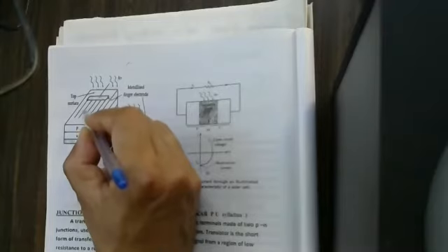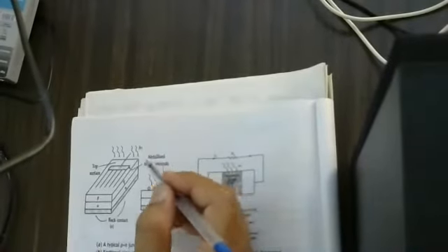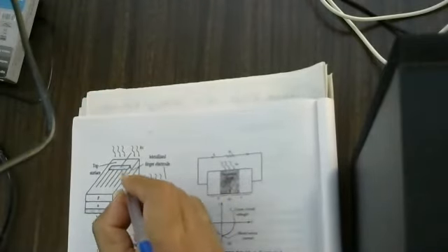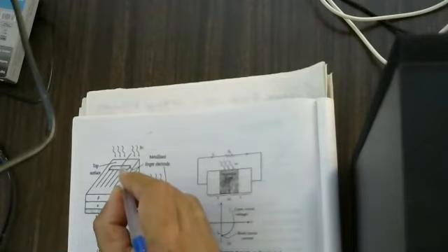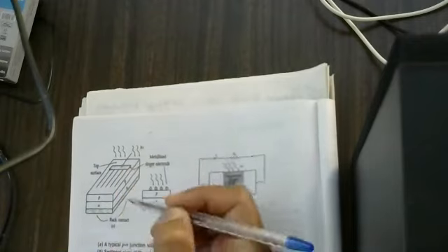finger electrodes. Just like our fingers, the electrodes are present. From one finger electrode to another, there is a gap. The gap must be there. If it is completely closed with a copper plate, light energy cannot pass through. For that purpose, we are keeping the finger electrodes like this. Now here there is a copper plate connected to the copper wire.